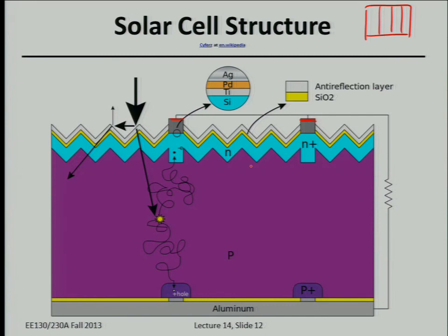Okay, so why is the surface intentionally roughened? Surface area. Oh, okay, that does happen, but that's not the reason why it's done. Less reflection. So that's what's illustrated here. You have light coming in. Some of that light will be diffracted and enter the p-n junction and generate an electron hole pair that can result in negative current. A part of that will be reflected, and if the surface is roughened, then that reflected light has one or more opportunities to enter the silicon again.